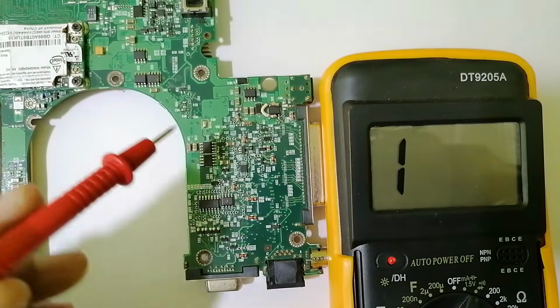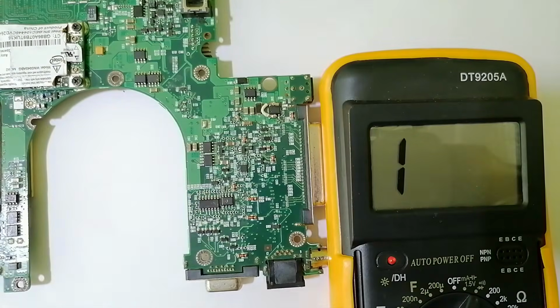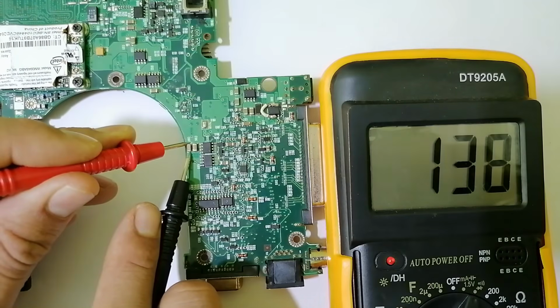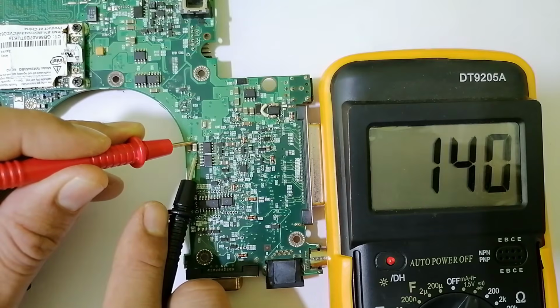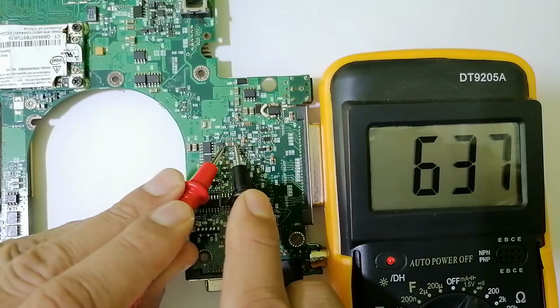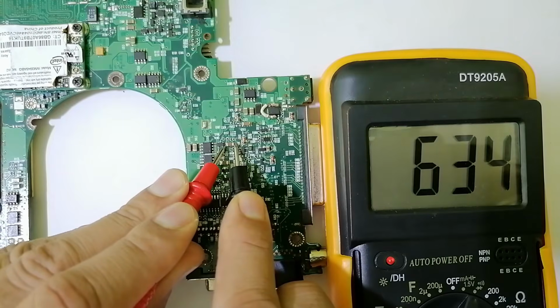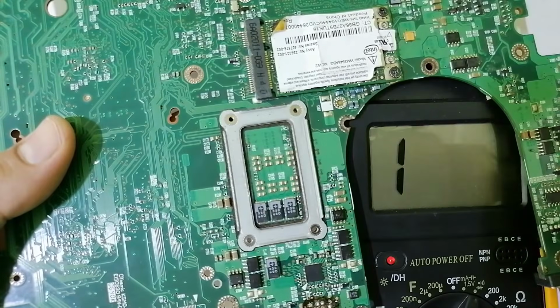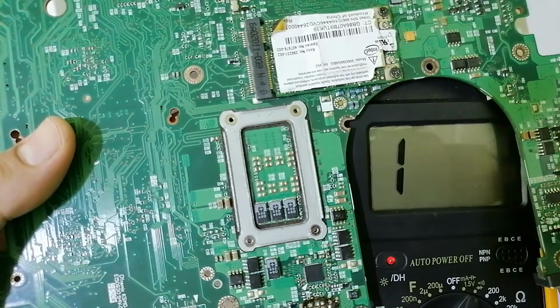But for the ceramic capacitors that do not belong to the CPU circuit or other chipset circuits, you will find a normal reading, as you can see here, for example. Do you see? Normal reading. Any ceramic capacitor here, if I find a low reading, means we have a short circuit. But here, guys, I want to add an exception.